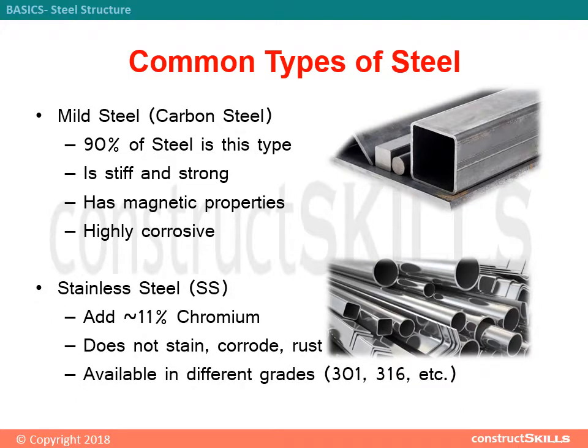Second is stainless steel. Add approximately 11% chromium. It does not stain, corrode, and rust. Available in different grades like 301, 316, and more.